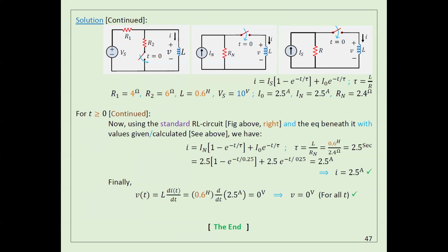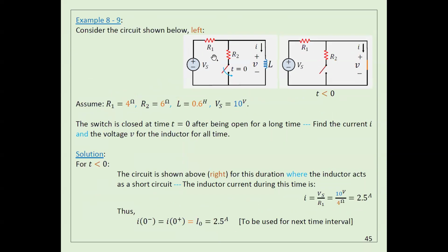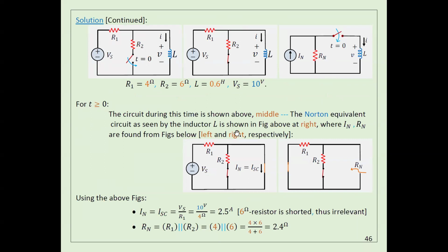Again, the circuit you are using to calculate V Thevenin, R Thevenin, I Norton, R Norton, I'm making changes to the original circuit to be able to calculate some parameters like I Norton and so on. This is the original circuit. There was no short circuit in the original circuit. I just added it. This is how we calculate Norton.